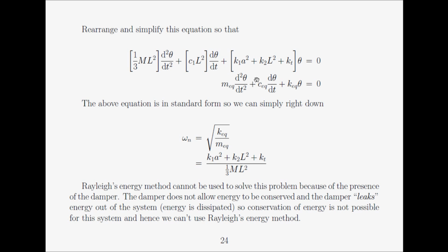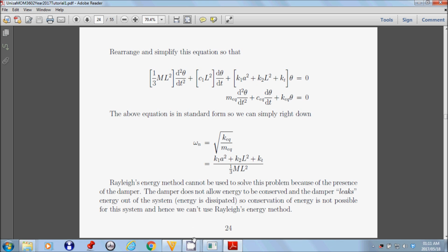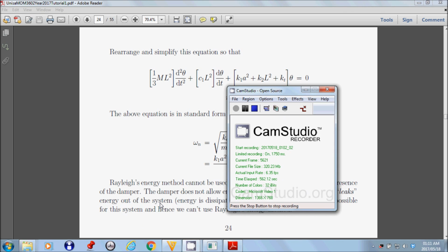So the main challenge of modeling systems is to put it in the standard equation, and then we can use our bag of tricks to analyze the motion, work out the damping factor, the zeta factor, the omega n factor, and so on and so forth, and solve the problem. And that is basically how we would go about solving question 2.